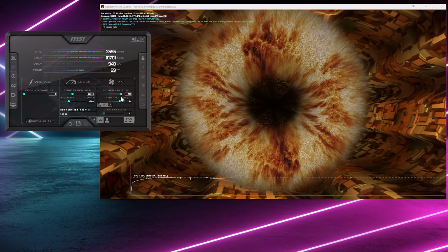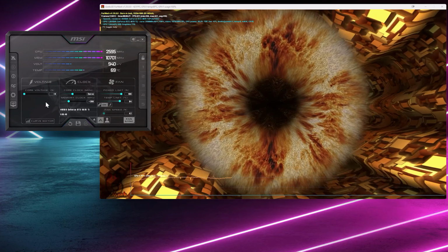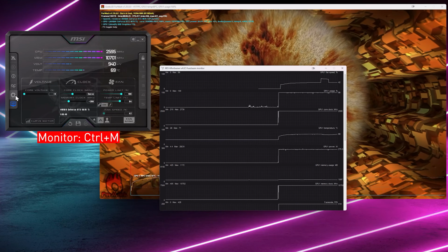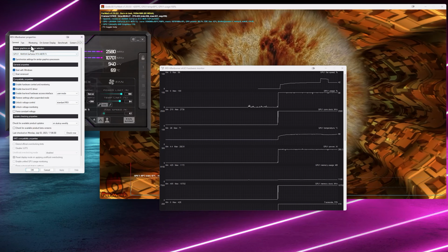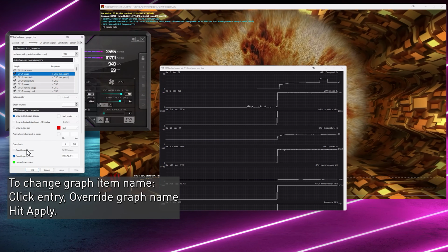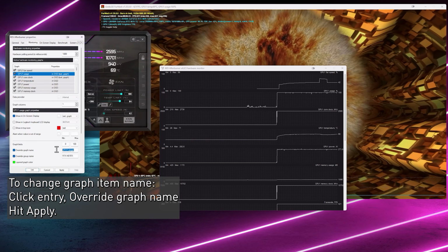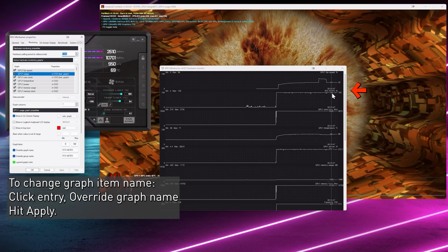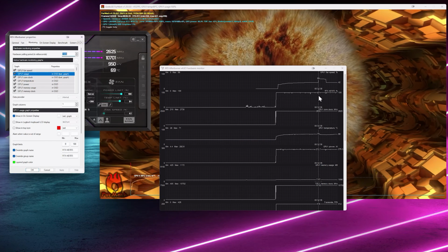Let's see how we can set a custom fan profile for our graphics card. We'll run a benchmark like Unigine Heaven or Furmark for a few minutes and keep it running in the background while you adjust fan speeds. Write down your frame rates and GPU temperature. When your GPU is running at max load, making your fans slower and quieter will start to overheat your card, and you'll lose FPS as the card thermal throttles.